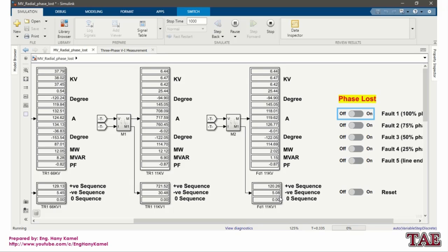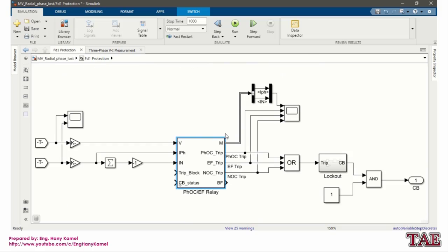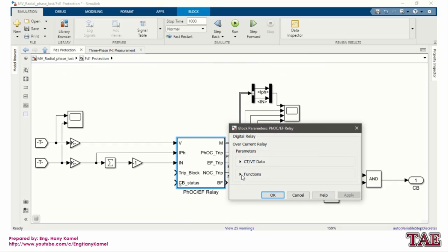So we can see now during loading condition, the system only has load, because it is an unbalanced load. This is 5 ampere in negative sequence current, and for removing only the last load it becomes 8 ampere of negative sequence current. So the minimum setting, we can put less than 8 ampere. And of course we need to distribute the loads to minimize the negative sequence during normal operation.